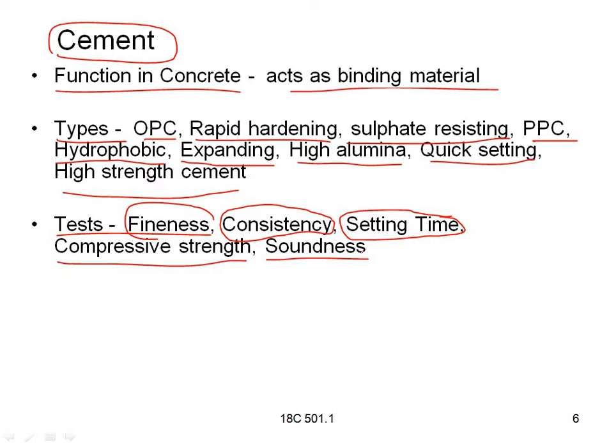So these cubes are made when the concrete is mixed, and they will be kept in layers in the cube molds. Up to 7 days we will keep them in the water, and after 7 days we take the samples and test them in the laboratory. Next, after 28 days we take them from the water and test them in the laboratory.